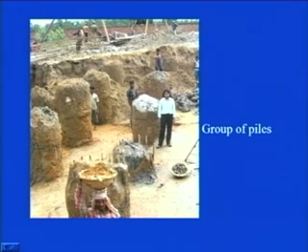These are all completed piles, and here you see, if you chip off some of the concrete from the top of this particular pile, the reinforcement will get exposed, as in this particular case. You see here, these vertical bars are seen in this pile, which is in the process, and in this particular pile it has not been chipped off. So, you can see that the concreting is done and a little bit of soil layer is also there.